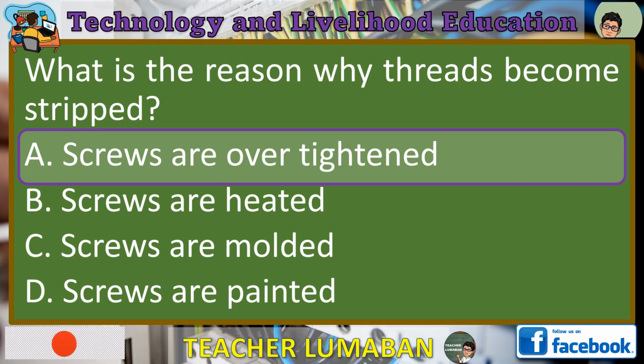Overall, the most common cause of stripped threads is over-tightening screws. It is important to use the appropriate torque and be mindful of the recommended tightening specifications to avoid damaging the threads.